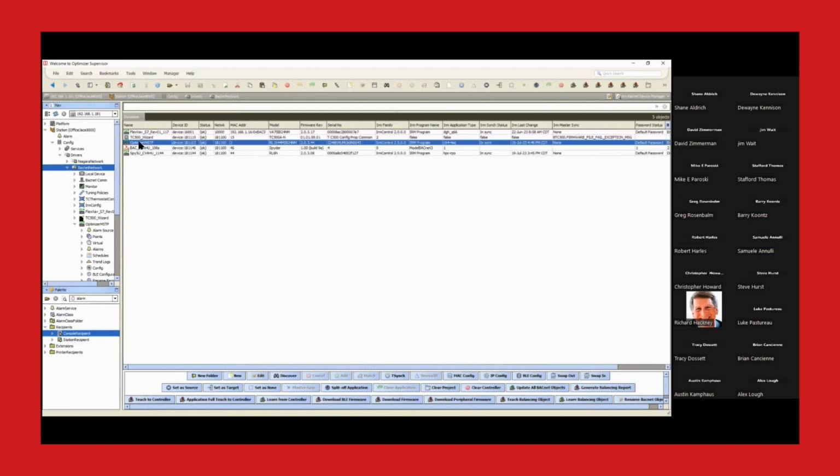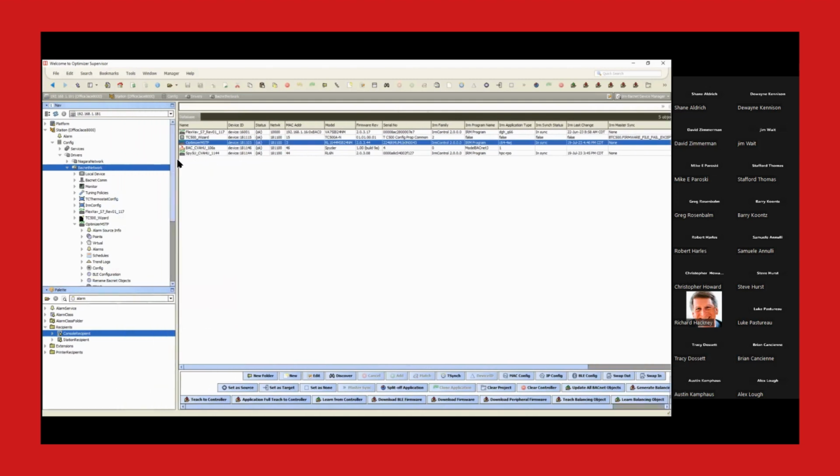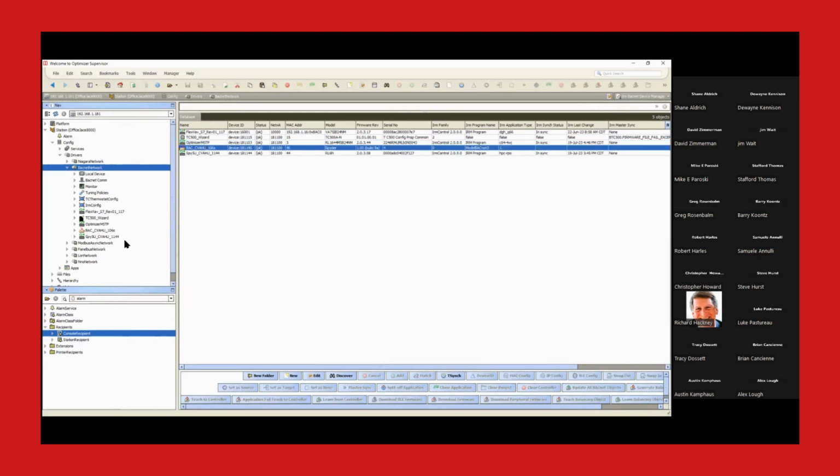Here's one of the new Spyder 7 MSTP controllers. So I'm not tunneling to it, I'm talking to it over BACnet. The Jace sees this optimizer Spyder 7 unitary controller the same way it sees that BACnet Spyder. So here's a BACnet Spyder. Here's an optimizer controller. It's just another gizmo on the twisted pair.